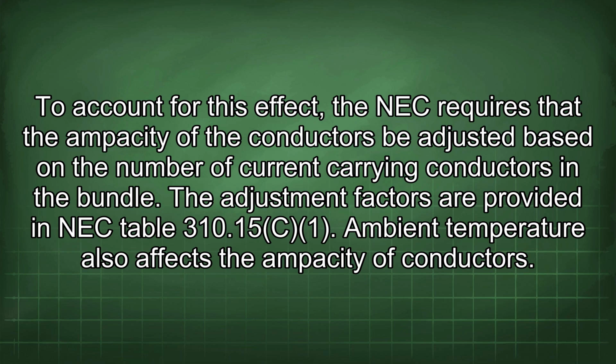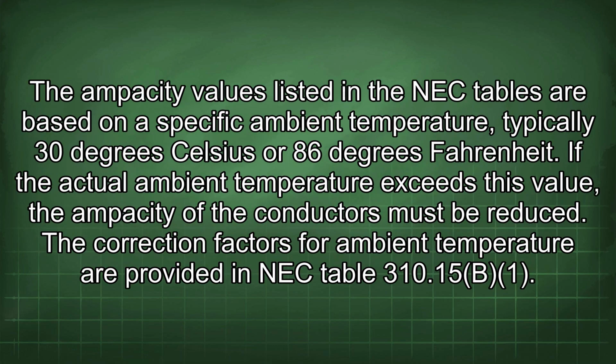Ambient temperature also affects the ampacity of conductors. The ampacity values listed in the NEC tables are based on the specific ambient temperature, typically 30 degrees Celsius or 86 degrees Fahrenheit. If the actual ambient temperature exceeds this value, the ampacity of the conductors must be reduced. The correction factors for ambient temperature are provided in NEC Table 310.15.